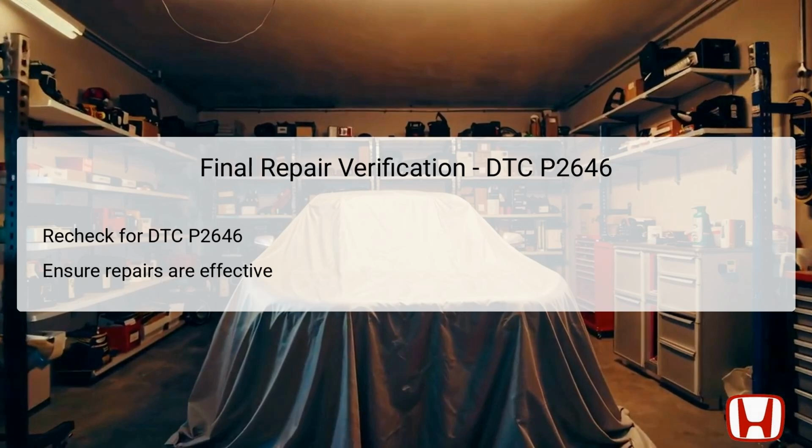After completing the necessary repairs based on the steps outlined in troubleshooting, it is crucial to conduct a final verification to confirm everything has been resolved satisfactorily. This means rechecking the vehicle for the presence of DTC P2646 using the HDS once again. If no codes appear, it suggests that all malfunctions have been rectified, confirming that the repairs undertaken were effective.